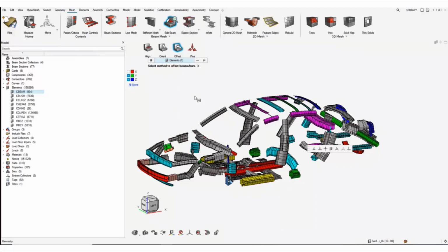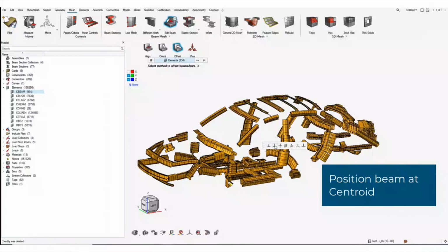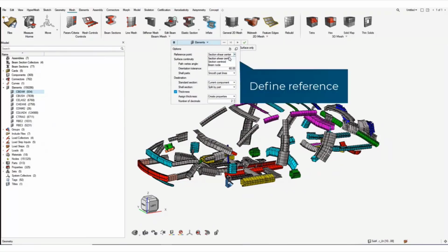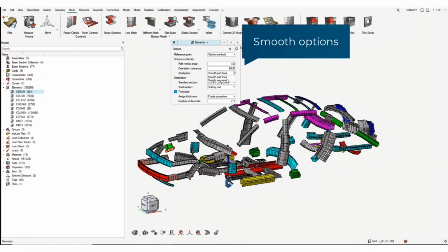To be more practical, and to avoid any mistake in offset, I will re-offset everything to match with the section centroid. So it allows not to have any issue with shear center wrongly defined. In the inflate, we have an option to say that the section matches its centroid, so the surface will be defined correctly.